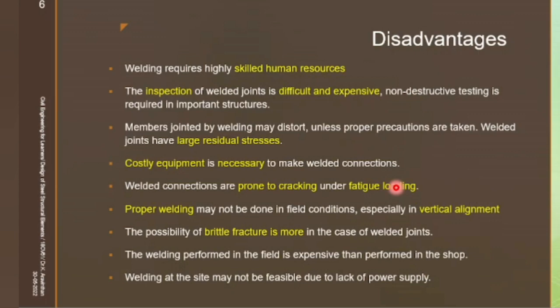A load can pass like that, so 20,000 cycles it will go down and up, down and up. This load is called fatigue: a continuous force which is acting, a small force but continuous. So a bolt can take fatigue stress, and weld has the disadvantage. It cannot take more fatigue stress, and is prone to cracking. So the welded connection has the possibility of cracking.